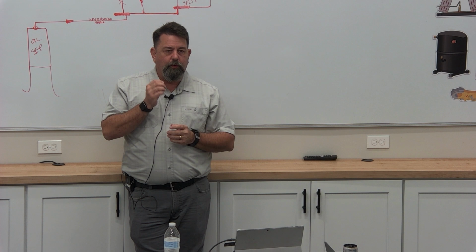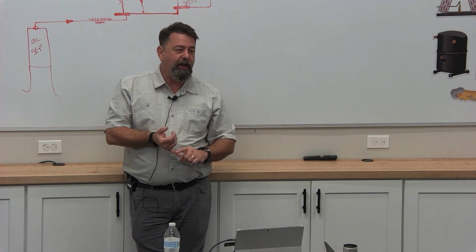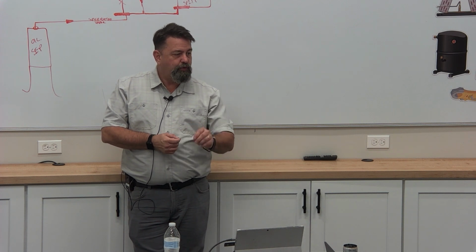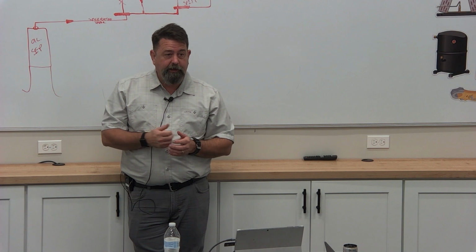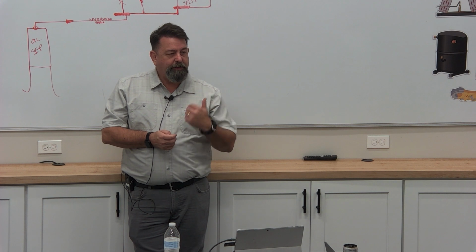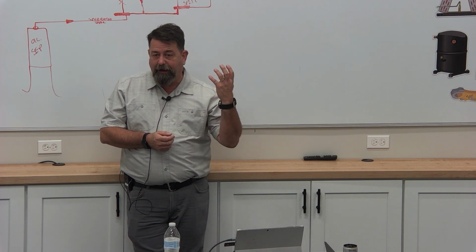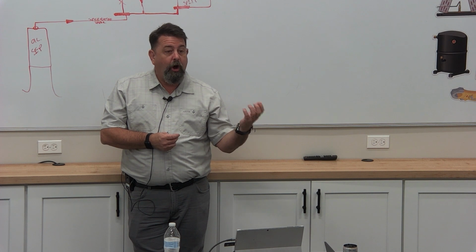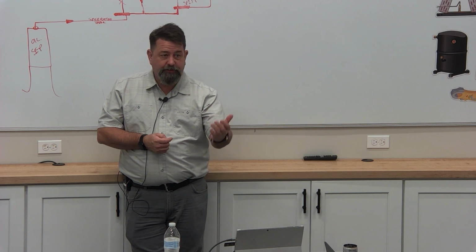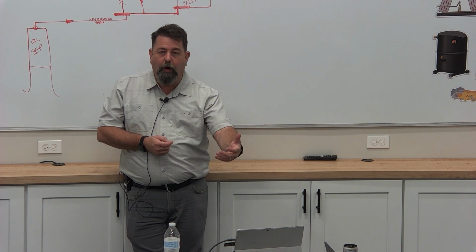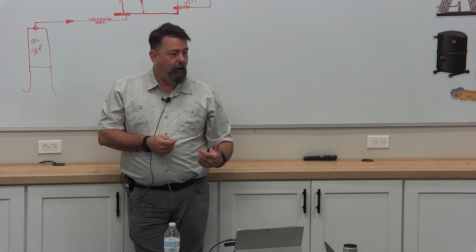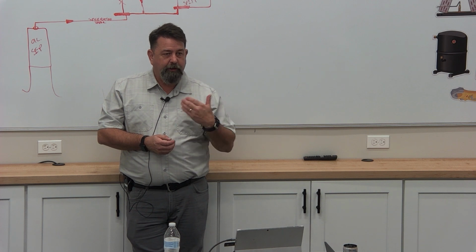Some case specifics. We shouldn't have to, and the reason we shouldn't have to is because we're gonna go back with the OEM motor. As long as we do that, especially the blade, as long as we go back with the OEM blade, then our RPM should be correct. The only time our RPMs will be wrong, if we go back with the original blade, is when I'm underpowering the motor, right? If I had a 6 watt motor, a motor that burned 6 watts, and I put in a 4 watt motor with the same blade, it's gonna run slower. That's the only time I'll have a problem with RPM, right? That's the only thing RPM would show me.